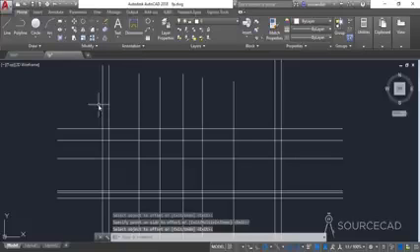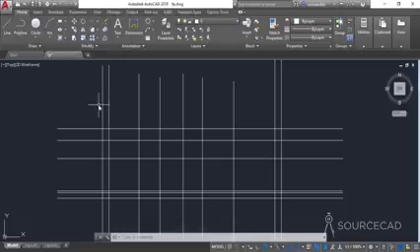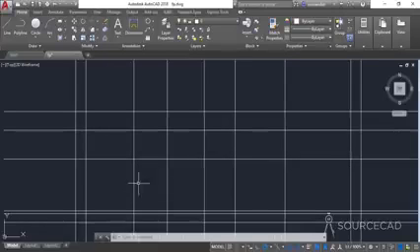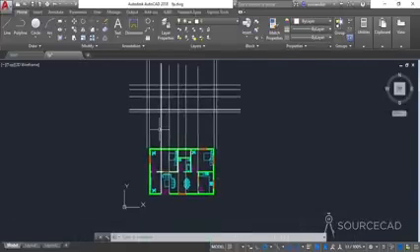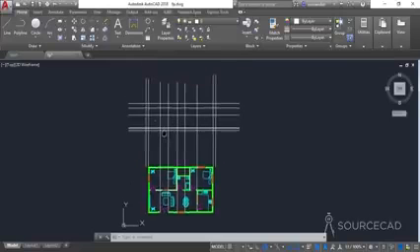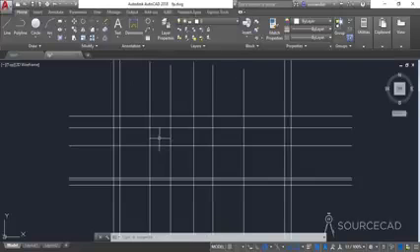So all of these distances are available in the data file which you'll download, and you can see the link in the description for downloading the data file or for downloading the elevation plan with all of these dimensioning. So you can refer to that dimensioning for making this drawing. All right, so we have done up to this much. Let's now move to this part here. So here we have this door, and if you actually go to this, you'll notice that this is the reference of door. So you can see that this is door. Okay, now here I'll add a line.